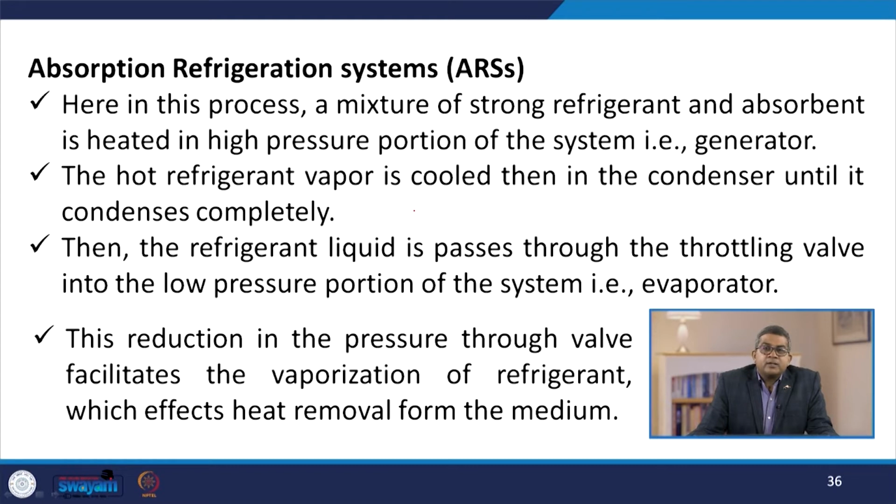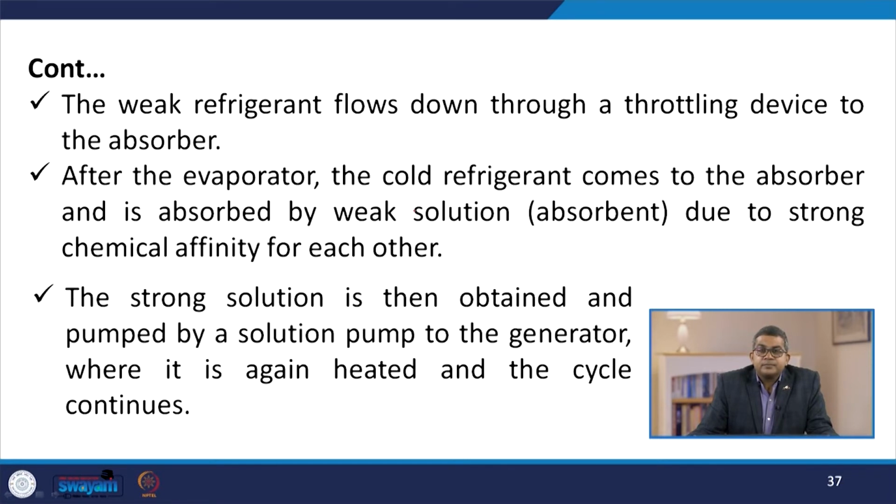The refrigerant liquid is then passed through the throttling valve into the low pressure portion of the system, that is the evaporator. Now, this reduction in the pressure through the valve facilitates the vaporization of the refrigerant, which affects the heat removal from the medium.